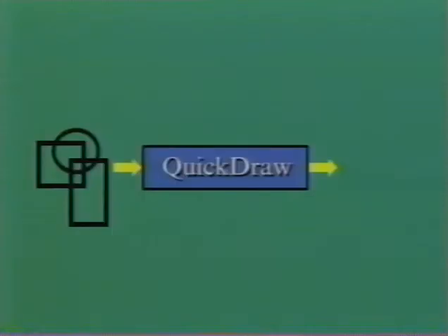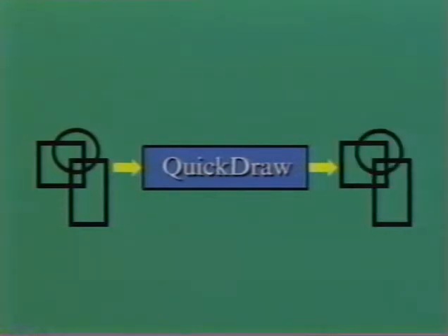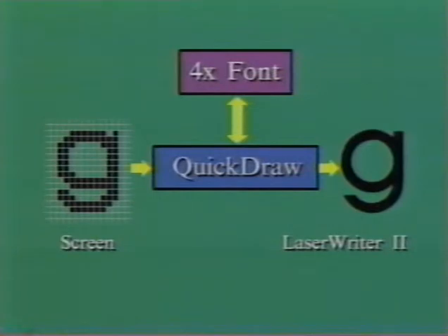In the Laserwriter 2 SC, the process of printing is somewhat different from the others, which use PostScript as a page description language. In the Laserwriter 2 SC, a screen object or character will be converted into a 300 dots per inch image by using QuickDraw. When dealing with fonts, QuickDraw uses the same standard font 4 times the size of the screen font. This conveniently makes the conversion to 300 dots per inch.